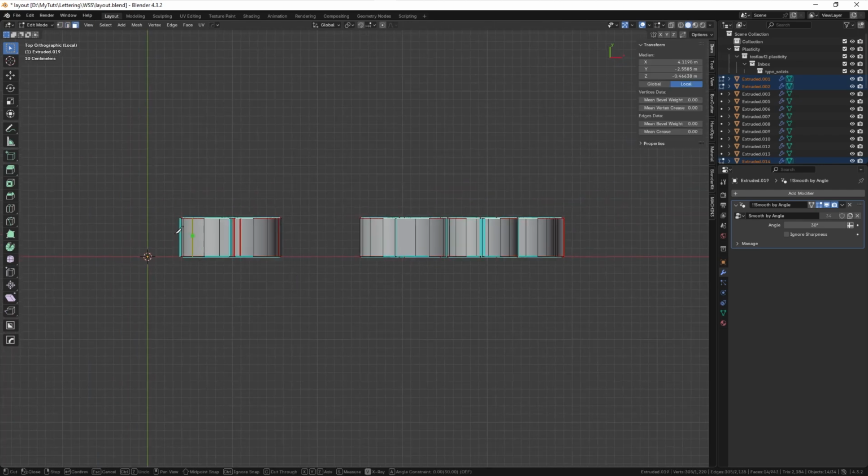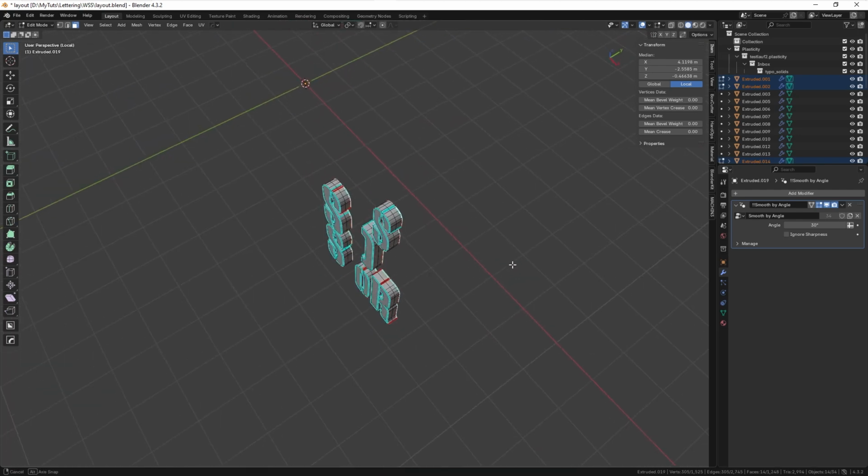I will simply press K for activating the knife tool. Start cutting somewhere here outside of these parts. Activate the knife tool, pressing K, and then start cutting. And then press A for making a straight cut. And then C for cutting through all the parts, not only the visible ones. And then click again and press Enter. So that's what we have so far.